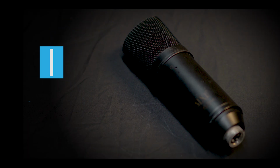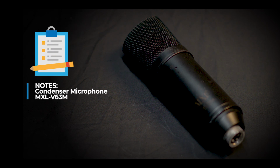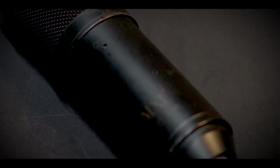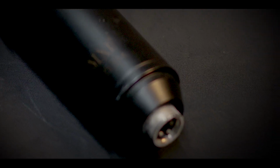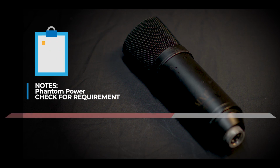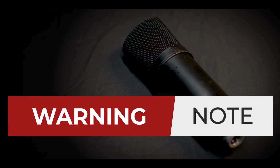This is a condenser mic, the MXL V63M. It too captures at low decibels, but higher than a dynamic mic. It also requires 48 volts of power, known as phantom power, in order to operate. Note, never apply phantom power if it is not warranted.